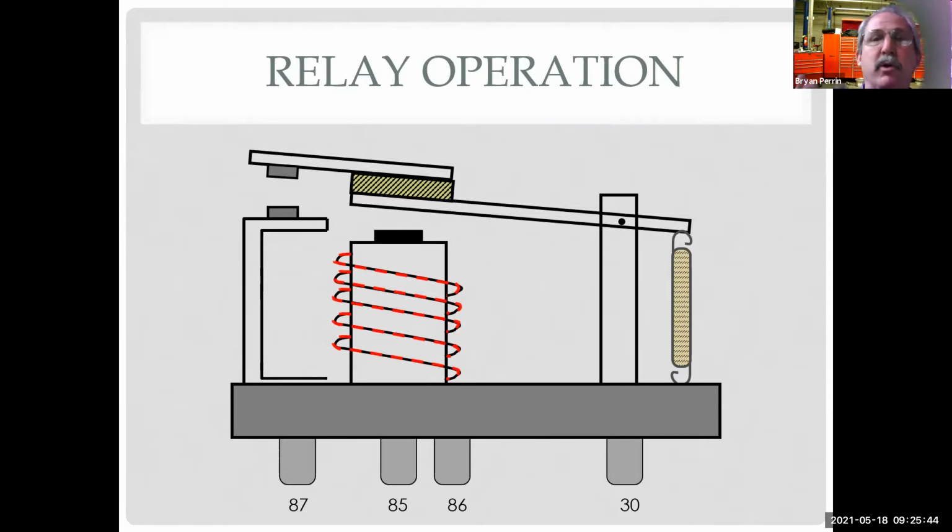So what we would do is we would go all the way back to the panel, grab another circuit, and run it from the panel at the house all the way to the kitchen, drop it down the wall, and put a new receptacle in there. Right, now I have two circuits in the kitchen. Now I can run my microwave and my coffee maker at the same time because I can put them on two different circuits.